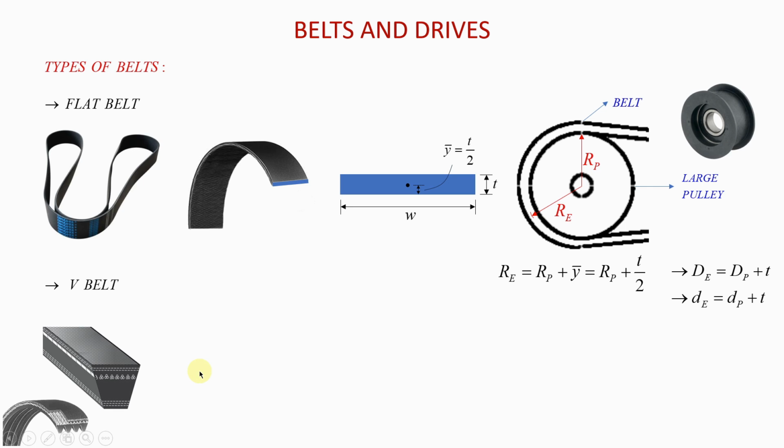that are joined together on one pulley. And so the cross section, of course, as you can see here shaded in blue, has the shape of a V. Very important. And since that is the cross section of the belt, you can expect the pulley to also have a shape in such a way that the groove here where the belt will come and sit is also in the shape of a V. Hence, it is called the V groove.